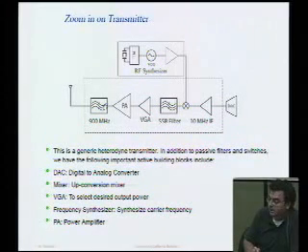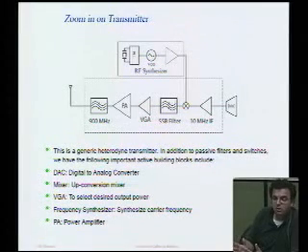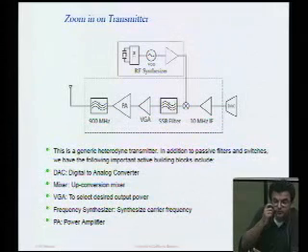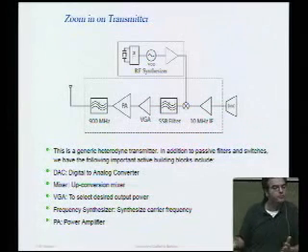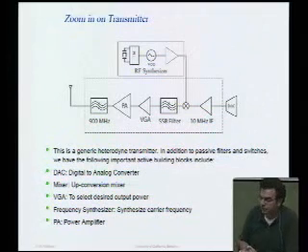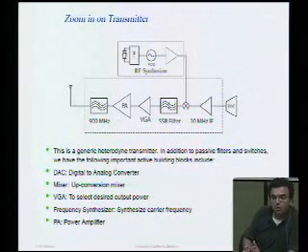A power amplifier is designed to put out a lot of power into the load. The load might be the antenna, it might be the cable that it's driving, but usually we'll find the load is a relatively small impedance, something like 50 ohms, 75 ohms, or 300 ohms. If you're looking back to your analog course, most of the loads that you're used to driving are capacitive loads, right? Or high impedance loads. In this class, often we'll be driving low impedance loads.